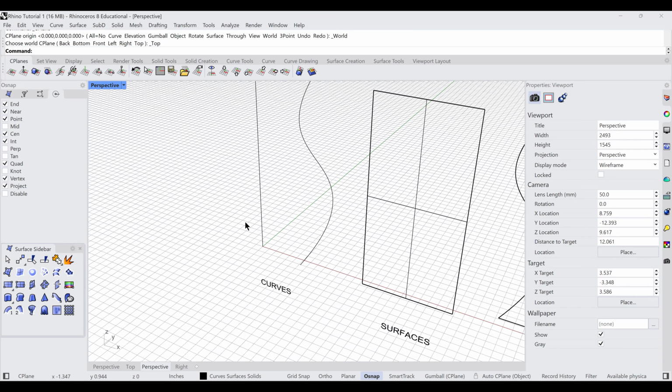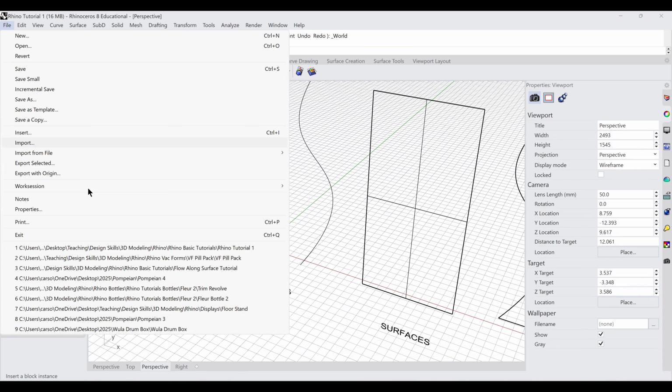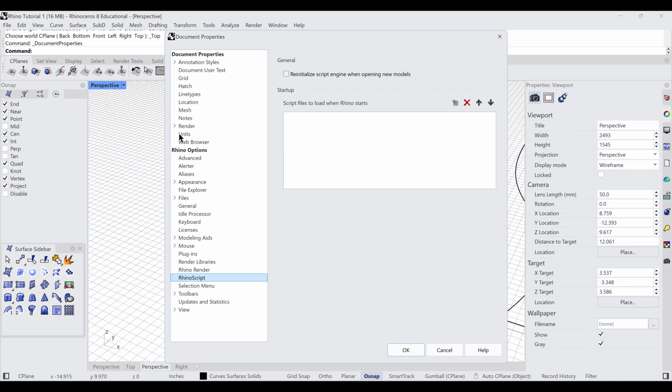You don't want to start building a little bottle and then have it 20 feet tall because the grid is out of scale and you're not in proportion. I mean, you can and then shrink it down, but it's always a good idea to work within a proportion and a scale that you can relate to. So let's talk about setting that up. If we go into File, all the way at the top left, and go into Properties, there will be a selection right here called Units.